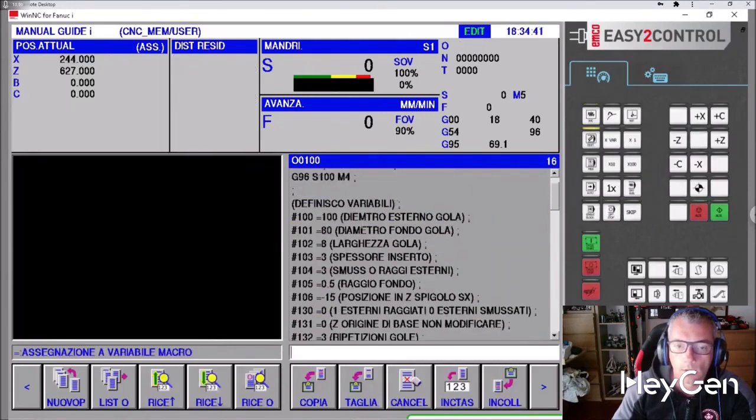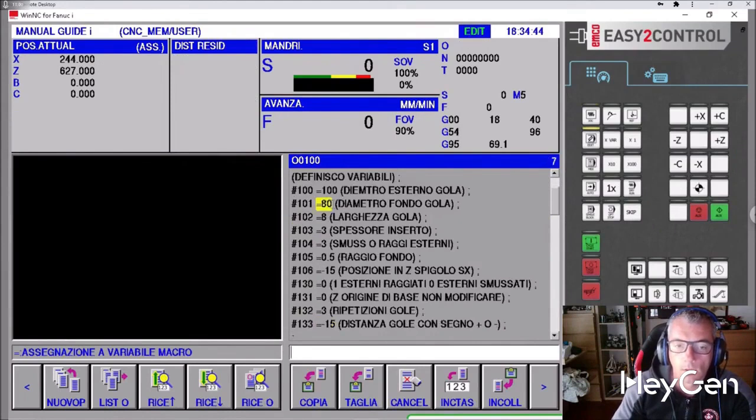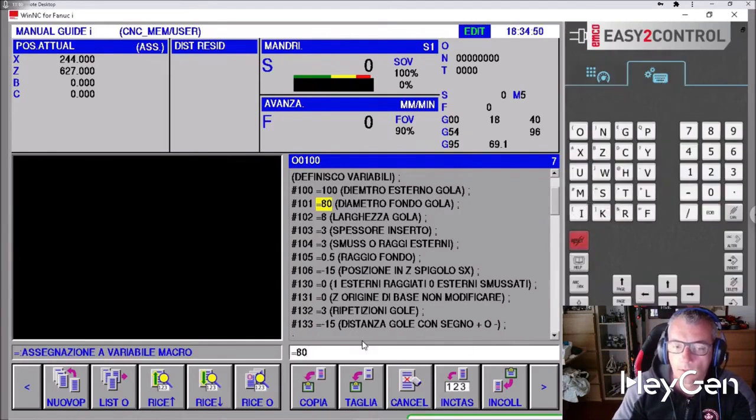I'm going back to my main program, and I'm currently telling it to set it to 70. We are focusing on ensuring that the grooves are not only deep but also sufficiently wide to meet the specified requirements. The target width for these grooves is precisely 5 mm. In addition, a chamfer of 1 mm is more than adequate. The process will commence from a starting point of 10.